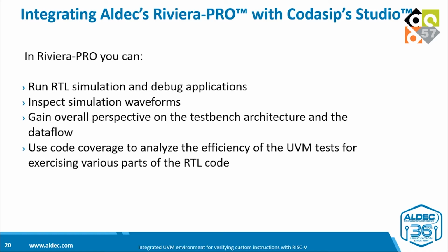You can inspect simulation waveforms and gain an overall perspective on the testbench architecture and the data flow. And all importantly, you have viewers which enable you to check out both functional and code coverage to assess how effective the UVM tests have been for checking the RISC-V design.